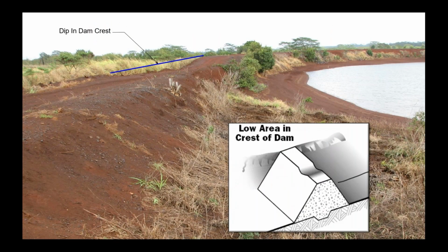So what do you look for in a dam if you're concerned about overtopping? Well, spillway capacity, obviously. You want to make sure you have enough spillway capacity, and you'd be concerned maybe of something like hazard creep. Maybe you have a low hazard dam or significant hazard dam, and now there's development downstream. And because of that, the spillway needs to be designed for the probable maximum flood, and it wasn't, because it never was intended to be that class of a dam.